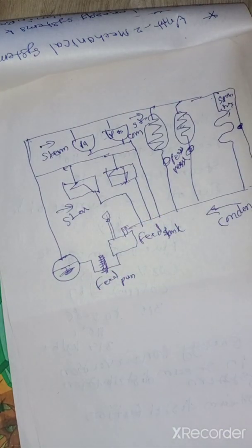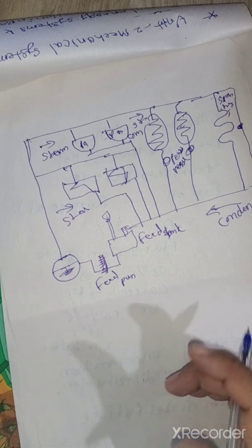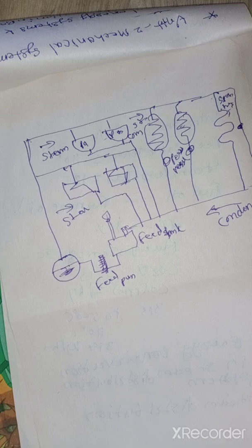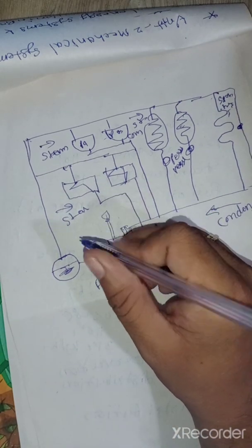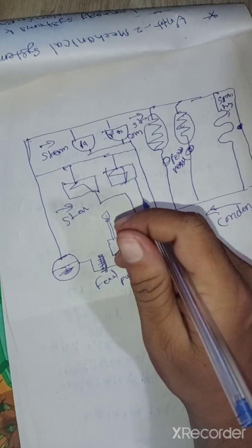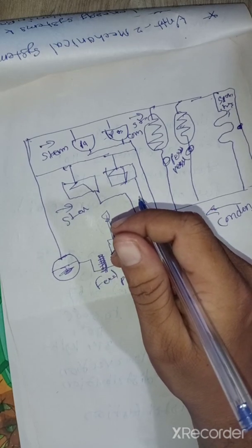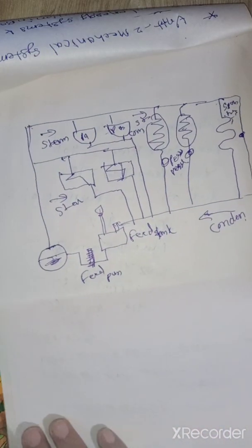The distribution pressure of steam is influenced by a number of factors but is limited by the maximum safe working pressure of the boiler and the minimum pressure required at the plant. As the steam passes through the distribution pipework, it will lose pressure due to frictional resistance within the pipework and condensation as heat transfers to the environment. Therefore, allowance should be made for this pressure loss when deciding upon the initial distribution pressure.